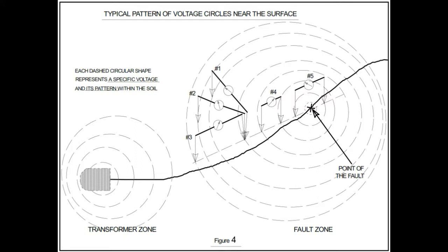In other words, you will have to adjust the needle back on scale in order to continue getting relative readings. If you selected the proper direction when you began to move your position, then you will get higher readings as you go. However, if you select the wrong direction, then your readings would show lower values than what you had in position 3. So it may be that you'll make 1 or 2 moves of the instrument before you determine which direction you should move to go toward the fault.